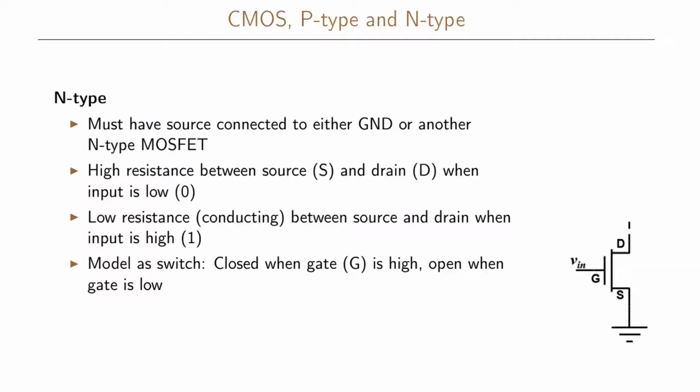The N-type MOSFET is the other type of transistor that we're going to look at. This N-type transistor is written typically in this way, and what we can notice here is that the difference between the N-type and the P-type is that we are lacking this ring that we had here for the P-type. We have the gate as being one of the inputs, and then here we have the drain, and this part is called the source.